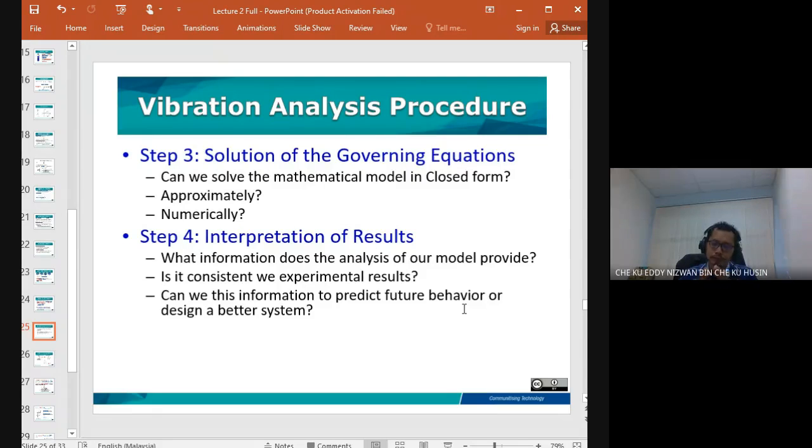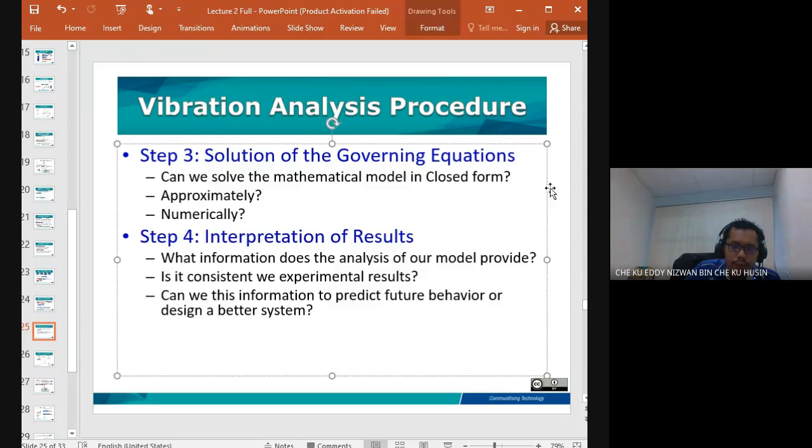Okay, so computational simulation. So you stiffen the structure and then you simulate. Now after you add a new structure, you change the structure, and then what happened to the natural frequency, the value of the natural frequency. Now you found that the natural frequency goes to 20, so this one is good. It means that you can apply your solution to the actual structure. So that's commonly how the linkage between the computational simulation and measurements works to solve the vibration.